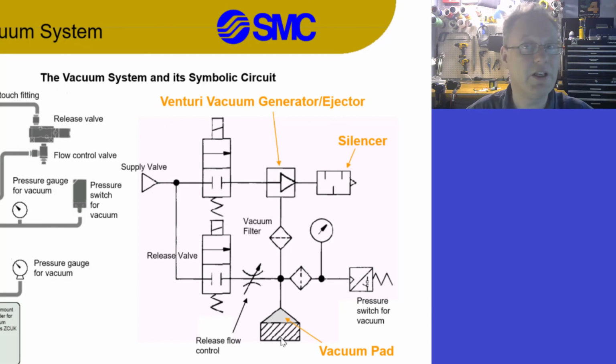Okay, now you want to release it. You turn the vacuum off. It could be a really good seal. So then what you do is you pulse this. This guy blows pressurized air into here. You can throttle it a little bit. It just needs to put pressurized air in there, so the vacuum is just gone. Once you do that, you're just filtering the air out here. It'll just go right out the actual vacuum pad.